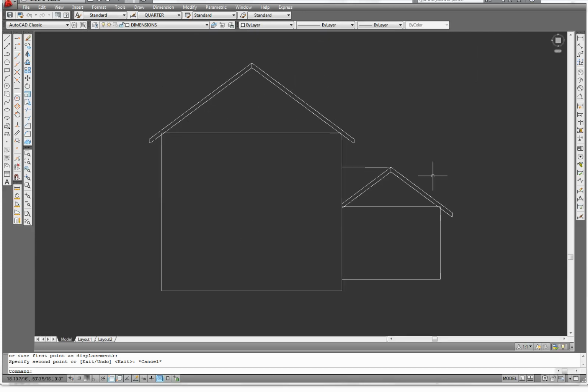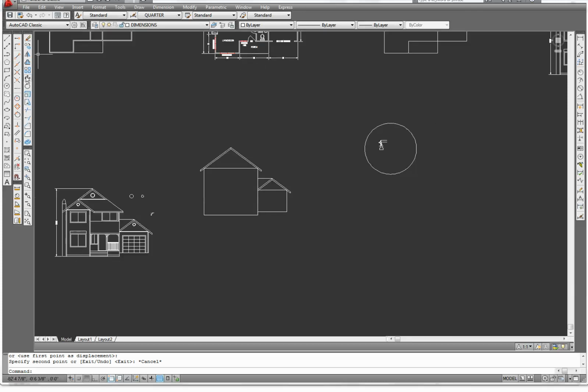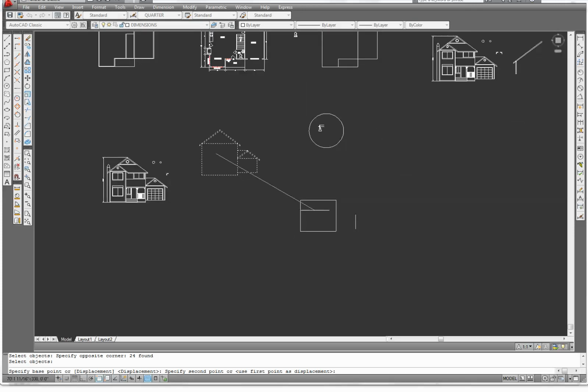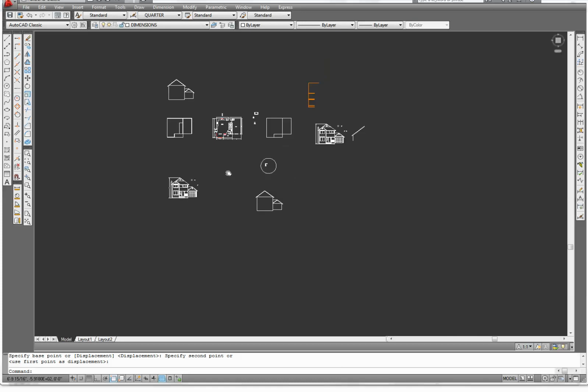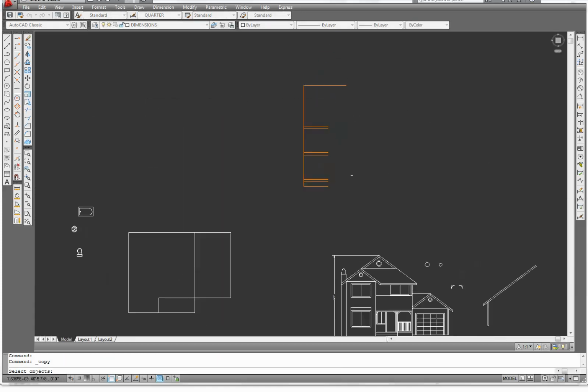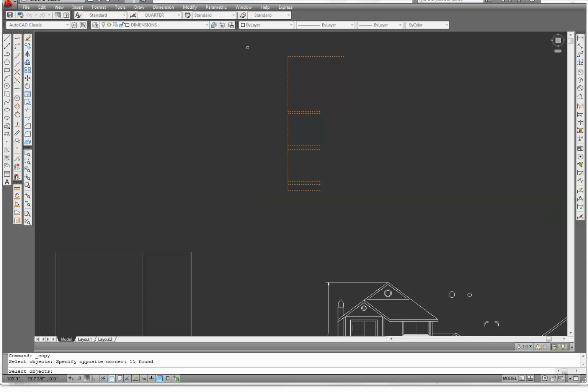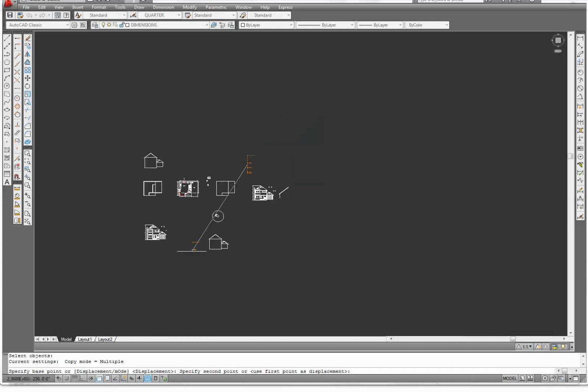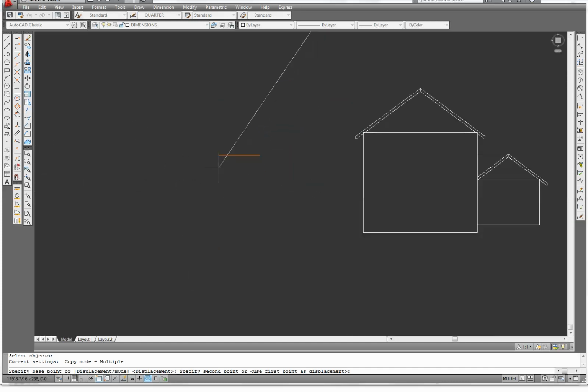We made a copy of this cross-section when we were drawing chapter 2 in the book. Now let's take it, use the move tool and move it well out of the way of the rest of the drawing. Now use the copy tool and let's make a copy of this story pole that we made and bring it down here. Just anywhere and set it close.